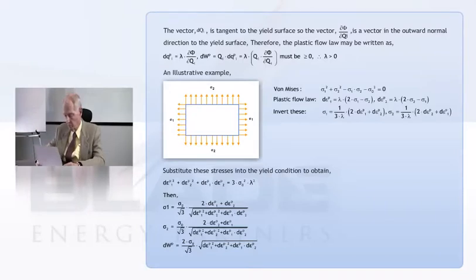Well, Prager works on the next slide. I'm just going to talk a little bit about this. He works a pretty simple problem. It's one that plasticians always seem to love to work on, including Hill: combined tension and torsion of a thin-walled tube. The reason anybody would do that is because it really is possible to run fairly intricate experiments on these. And thin-walled might mean a d over t of 20 to one person and 50 to somebody else.